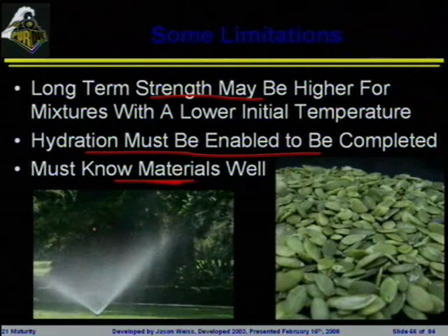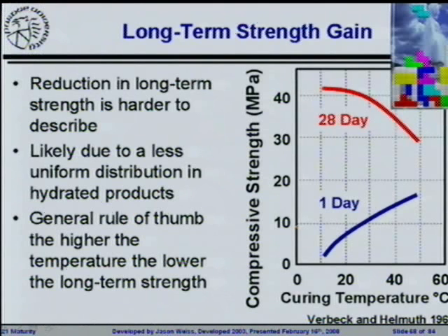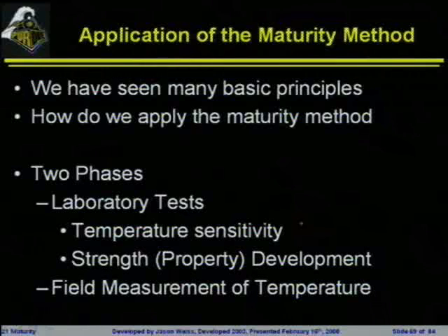So it needs to stay wet because if our materials don't stay wet, hydration can't take place, and we're just going to have a bunch of old lima beans or a bunch of old grass seeds that started something and really couldn't finish it off. So we've talked about this idea of the fact that the microstructure can't develop. I think we covered this fairly thoroughly last class, again, on why it's a limitation.